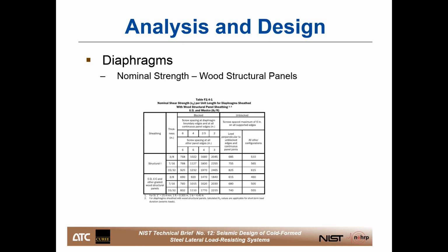And again, what you're going to get from S400-20 is the strength and stiffness of the membrane portion of the diaphragm. The cords and collectors and stuff you'd still need to design based on other modeling or basic mechanics. And of course, other diaphragms can be used. AISI S400 does not limit you to these particular diaphragms, the profiled metal or the wood structural panels. So you can use other types of diaphragms like proprietary systems based on manufacturers' published data or based on principles of mechanics if you've got the information you need to perform the analysis.